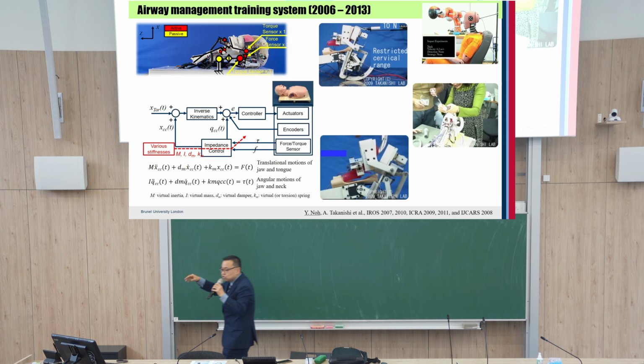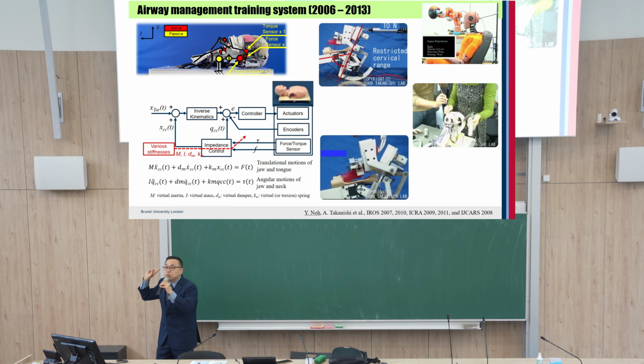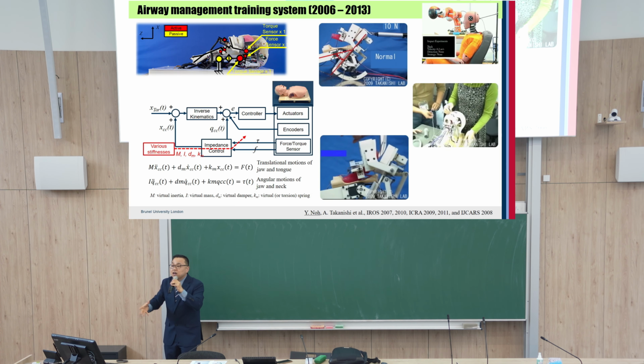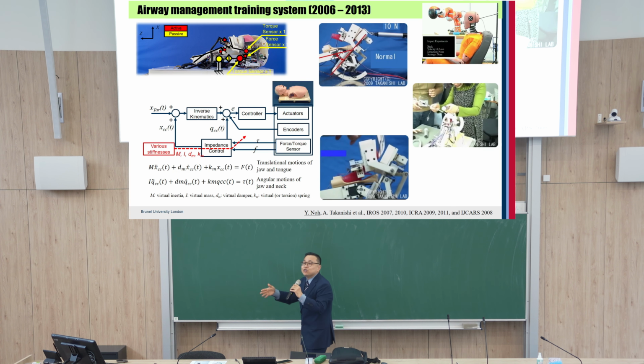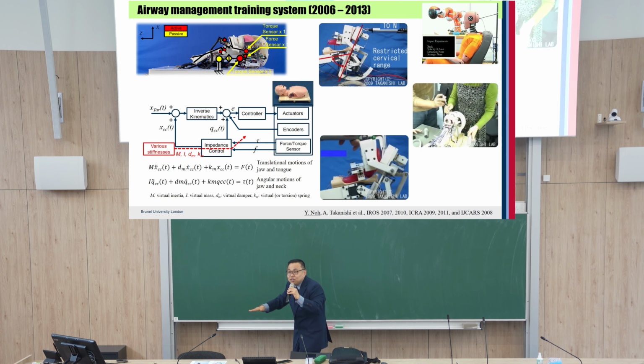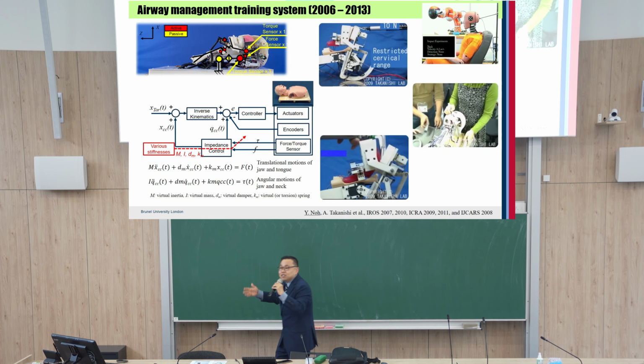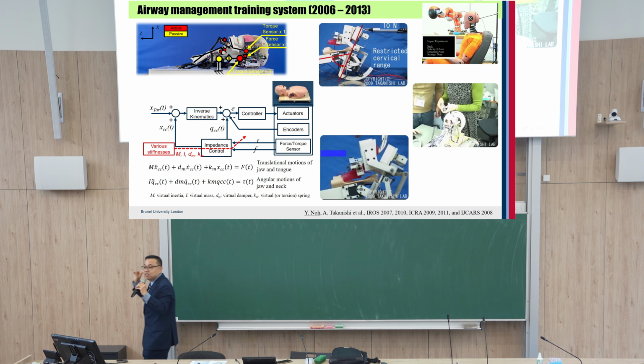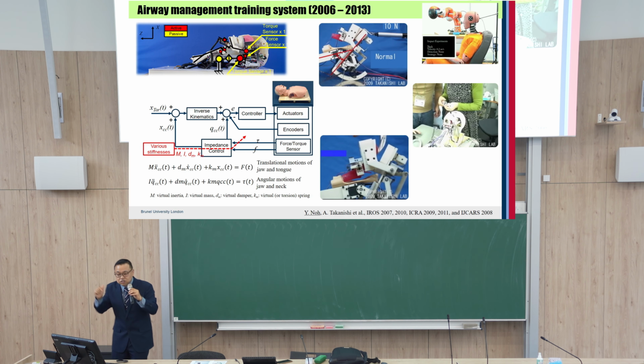Impedance control is implemented in this patient robot system, and its behavior looks like the robot has actual muscle. Before injecting anesthetic, the robot joint is very stiff, so you cannot easily rotate the tongue or head. But after the medical doctor injects anesthetic, the impedance coefficient suddenly becomes lower, and all the joints become very relaxed. That's why impedance control is implemented in this robot system.